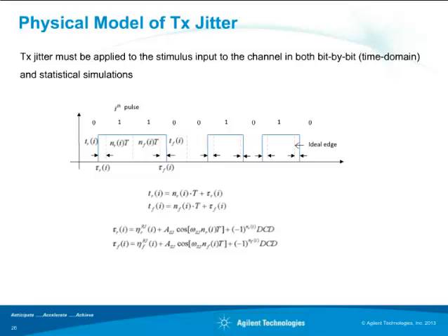Next question is also from Saeed. He said, should the jitter depend also on return loss? Does jitter amplification depend on return loss? In general, yes. The way that jitter amplification depends on return loss is actually included in the channel transfer function.